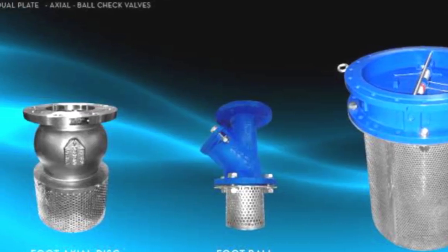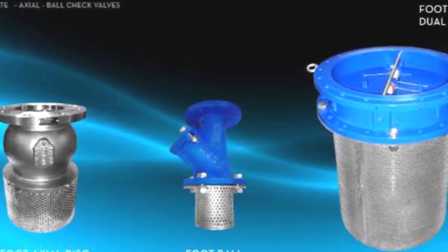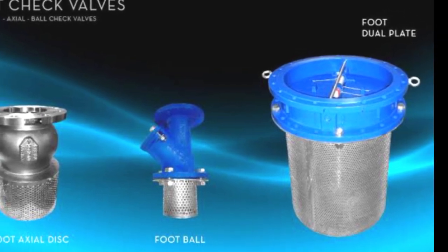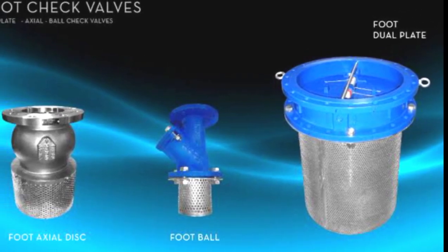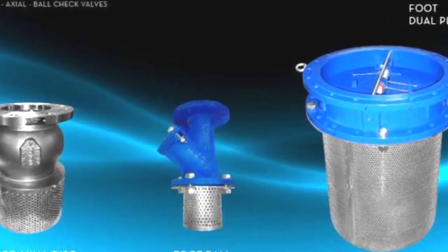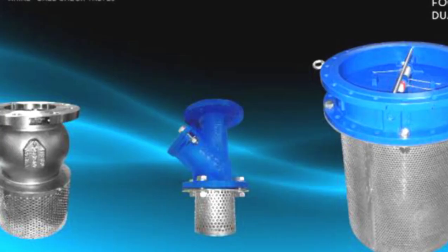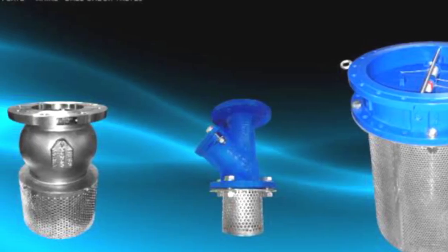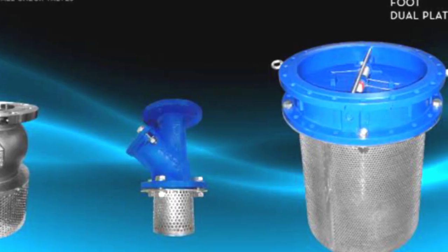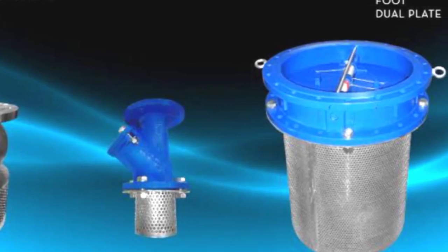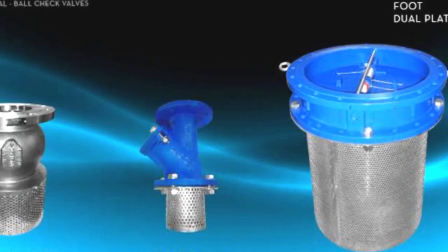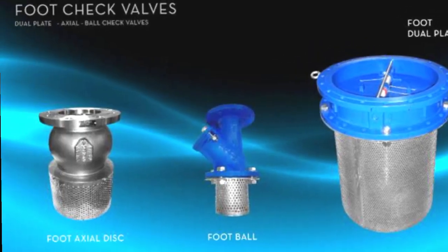Float valve. The float valve has a ball float attached to a lever. As the water level rises, the float goes up and pushes the valve closed. When water goes down, the valve opens to refill. Used in water tanks, cooling towers, and sometimes in oil tanks. Not used in steam, gas, or slurry systems. Float valves are simple and automatic, used for level control in storage tanks.